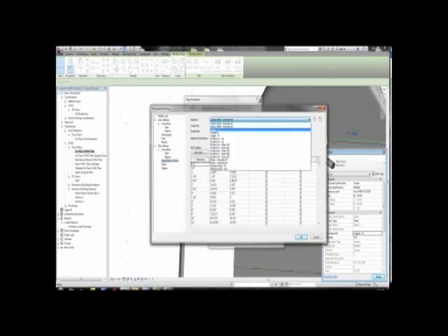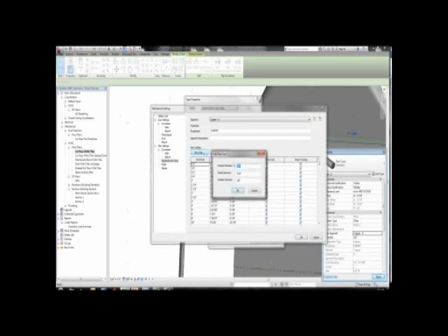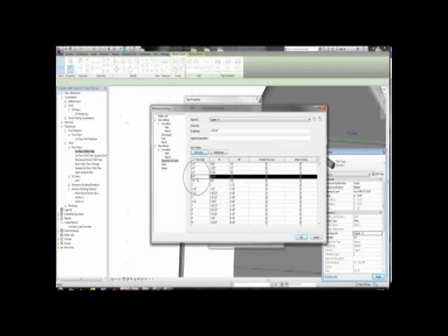So let me jump into the segments and sizes, which I can access through type properties. I'm going to go to my copper K. And once I have the copper K selected, I'm going to add that new size, which is going to be that 5/8 of an inch pipe size. Once I get that in, I can also go to the pipe specifications, and I'll add in the inside diameter, and I'll also add in the outside diameter. And then typically we could just use that, if we want to add that in the sizing list or used in sizing, the same applies on the right-hand side.